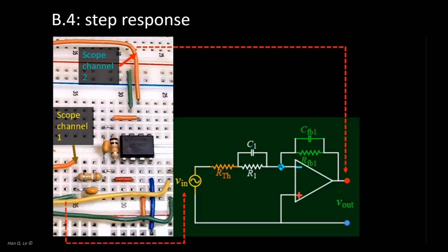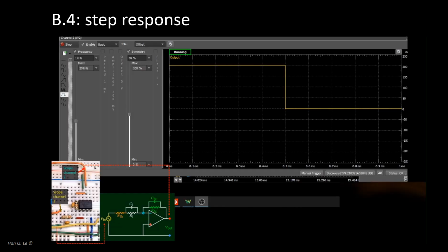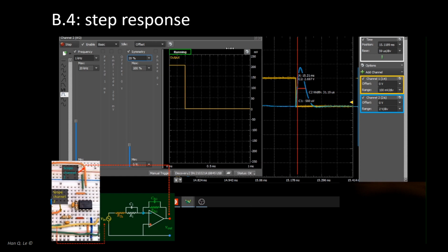This part is quite interesting. What is the derivative of a discontinuous step, mathematically known as the Heaviside step function? It is an impulse function of infinite magnitude, also known as the Dirac delta function. However, a real physical system can only have a finite response, and the output impulse has a finite time duration that is inversely proportional to the system bandwidth.